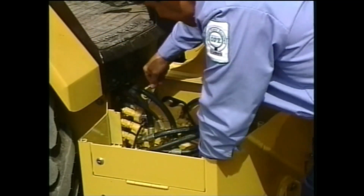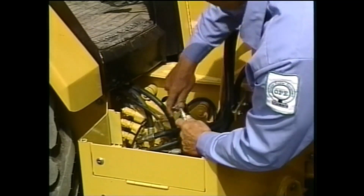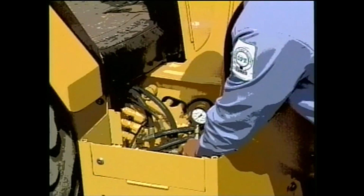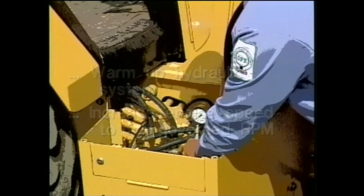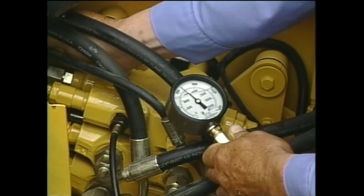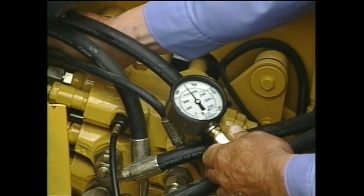To adjust the circuit relief, install a pressure gauge in the test port the manufacturer provided or install a T-fitting between the pump and the system relief valve. Warm up the hydraulic system and increase engine speed to full governed RPM. After the oil reaches 120 degrees Fahrenheit, slowly turn the adjustment screw 1/8 turn at a time while observing the pressure gauge.